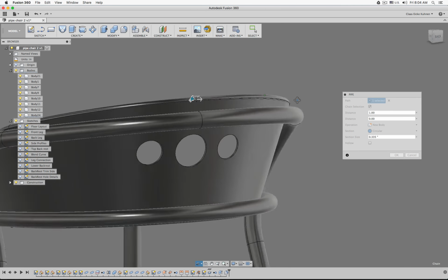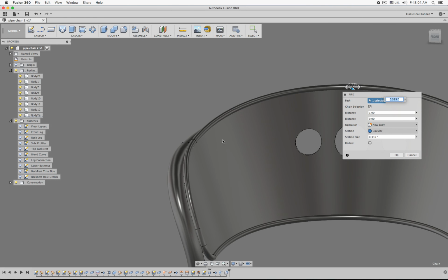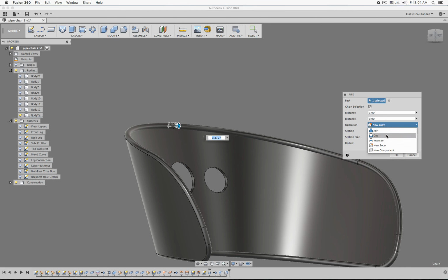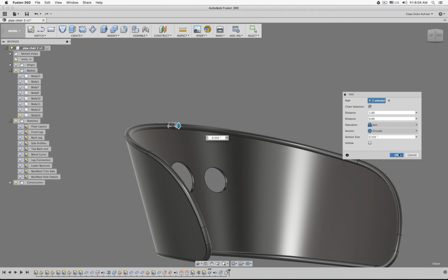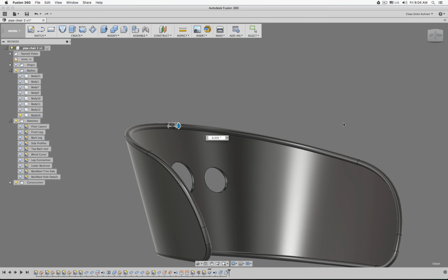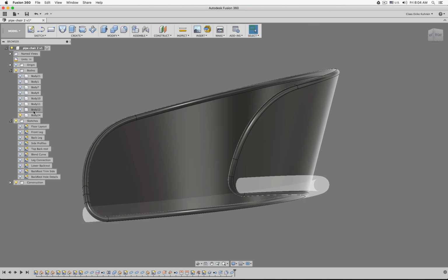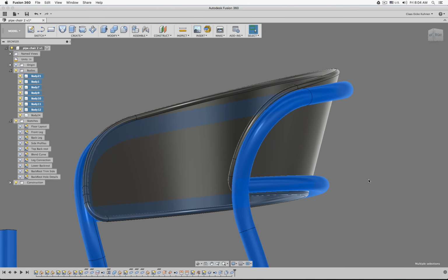And when we now do a join, we do not really want to see all the different pipes, because I could by accident fuse all these parts together. So all this I hide there, okay. And now I could say join, click OK, and we should be good now. There, and then all those I could show again.